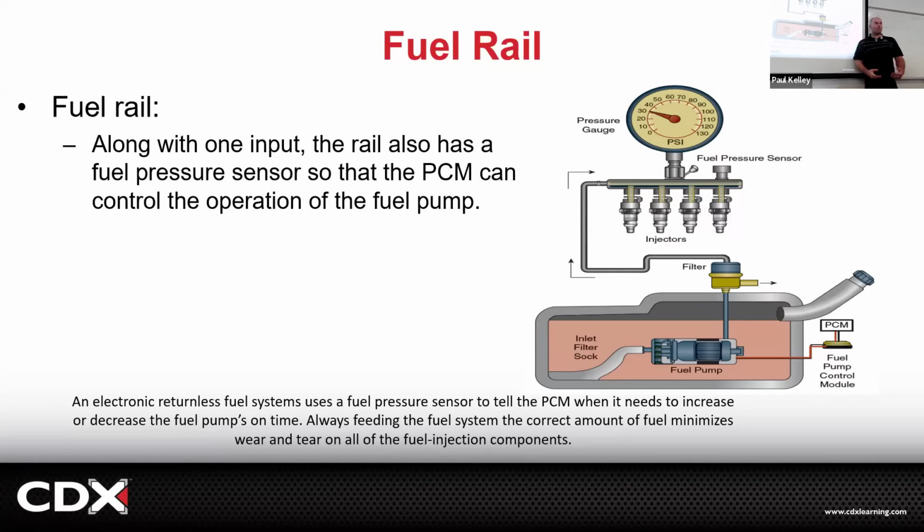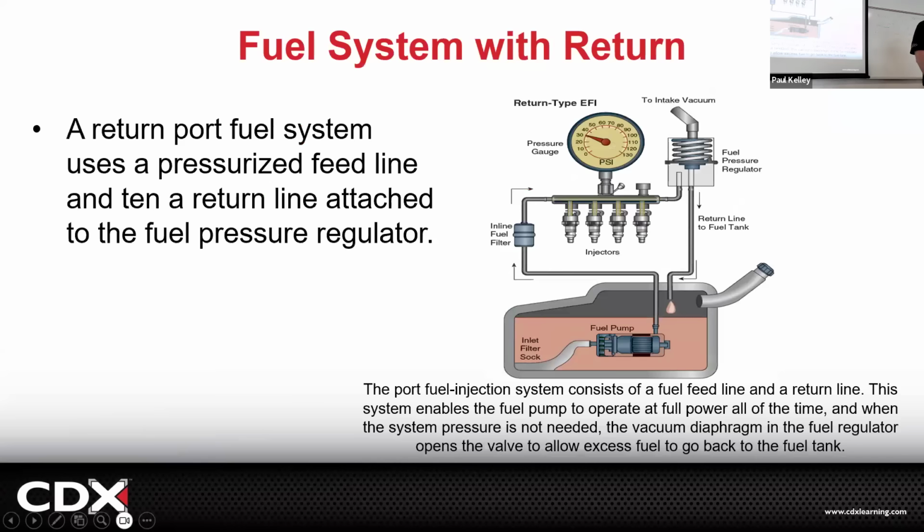Scan tool it. That's what I'm all about. I'd be like, I'm not even getting the gauge out. Let me check the fuel pressure on the scan tool. Oh yeah, 30 PSI. Yeah, exactly. Live data. That's a parameter ID, a PID. That's nice, right? So kind of similar.